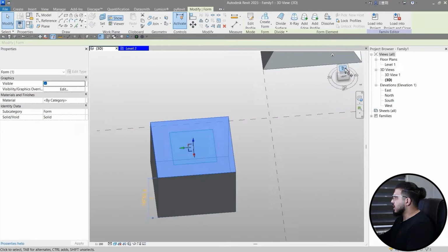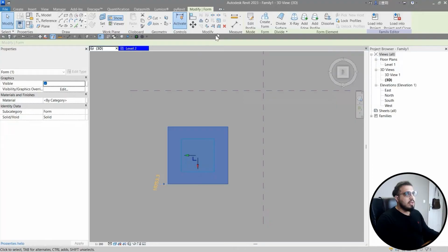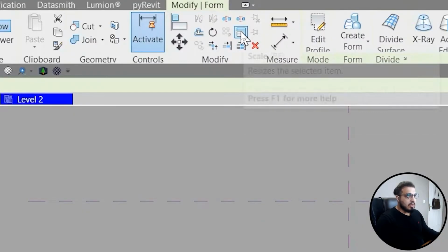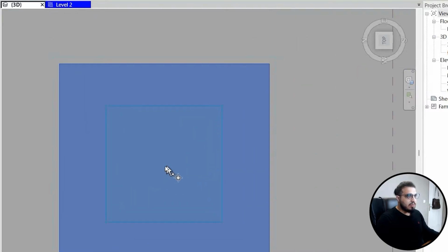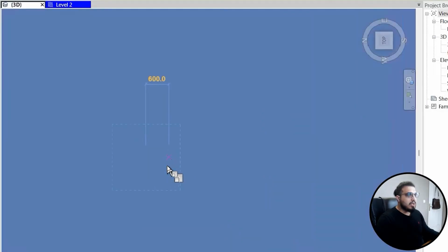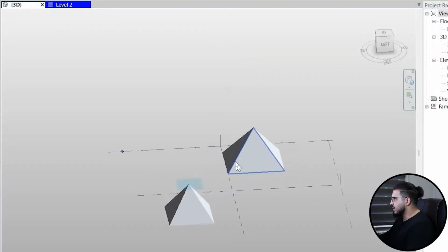Now we have an option on each face that you can rotate them. Also, you can scale them. For example, let's scale this part. Let's click on scale, and let's scale it from the center to some points around here. Click once in here, click again in here, and now you can make it much smaller. But it can't be zero. It needs to have a really small number. For example, like this. And now we have a pyramid with another technique, and you learned about scaling the faces.